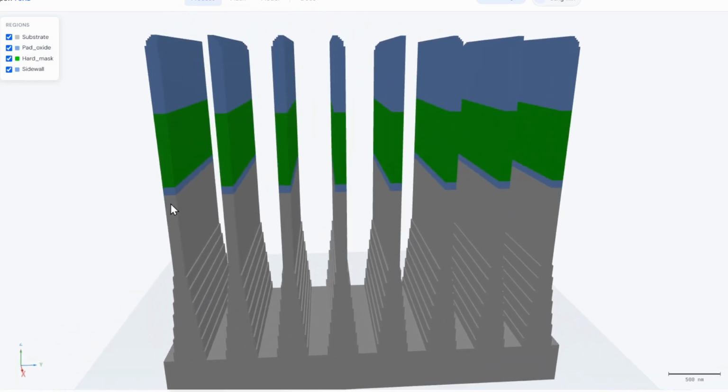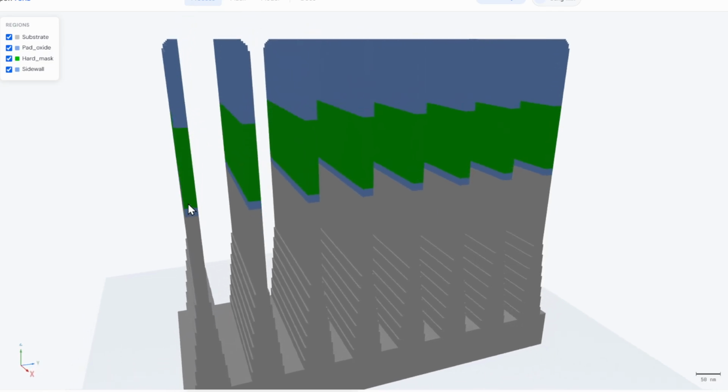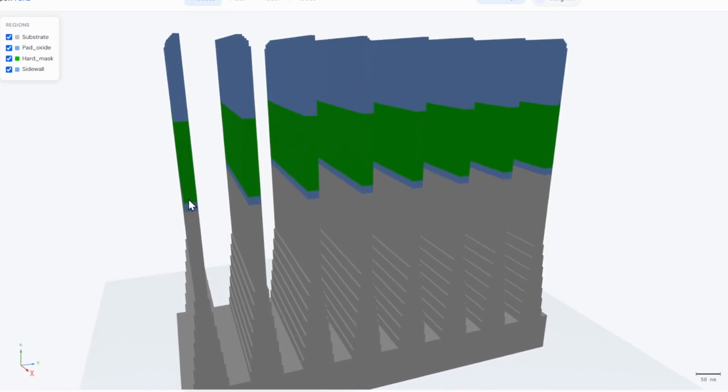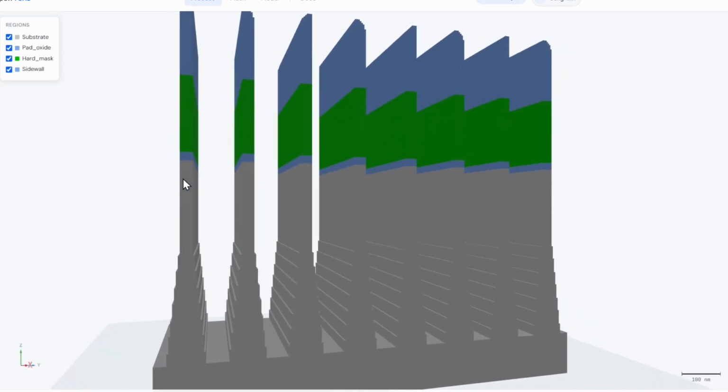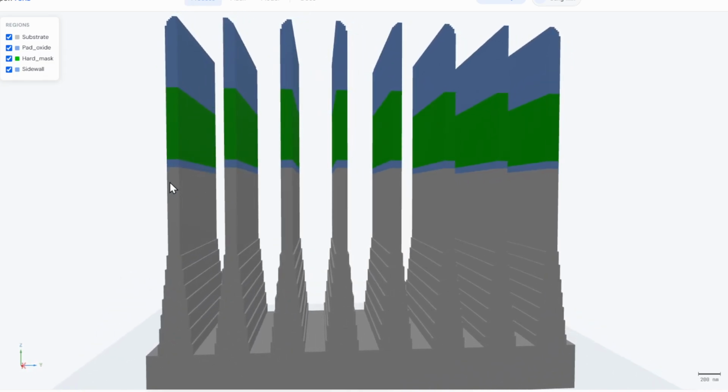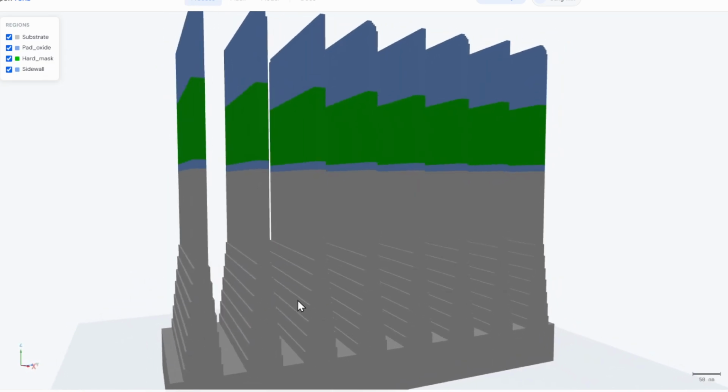In order to make the combination of mechanical stability and also good short-channel immunity, we intentionally perform such a two-step etching.